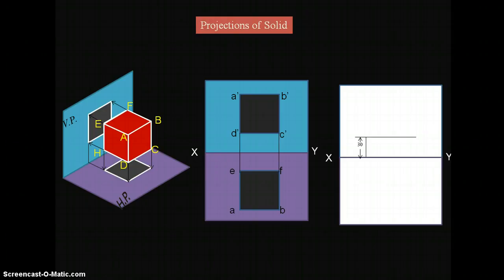On this I have drawn the projection line also. From this projection line, start the square with the size of 30 mm. All the sides of the square should be 30 mm only, because square means all the sides are equal. Using the 30 mm side size, draw the square and finish the other projection line like this.